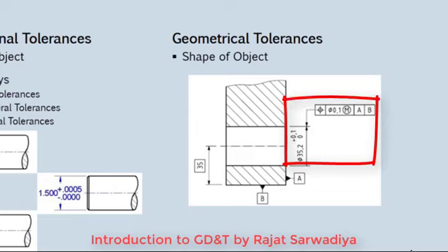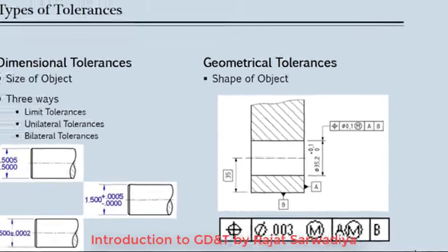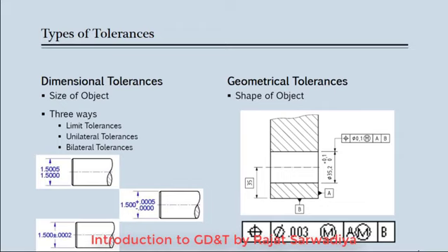You can see there is a hole of 35.2 diameter, and there is one frame, one geometrical tolerance applied on that. We will understand the meaning of that as well. That particular thing is your feature control frame, which controls and manages the complete information about that geometry, its dimension, and its tolerances along with the references as well.